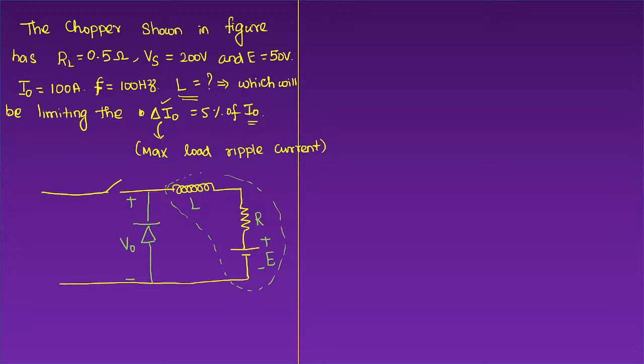You can directly say that if I measure the voltage across these two points, or if you measure the voltage between these two nodes, both will give you the same result, because the inductor behaves as a short circuit when it is connected with the DC supply. So input is as usual connected with the supply voltage Vs. Okay, now you can start your operation. Try to figure out the value of inductance L. That's all.